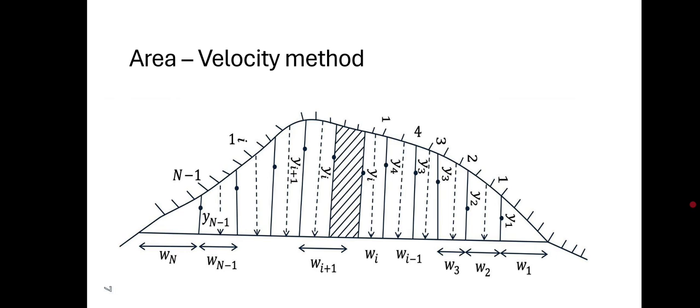We find how much water is there in the river or stream. The term flow rate or discharge describes the volume of water flowing per second in the stream. There are many direct and indirect methods of analyzing this discharge. One of the methods is the area velocity method.